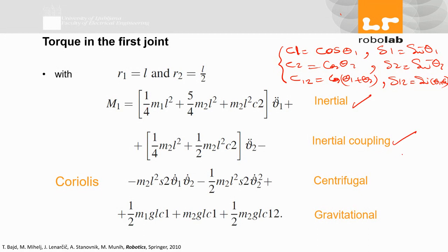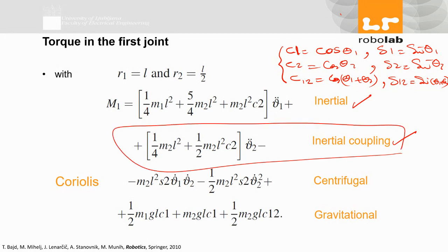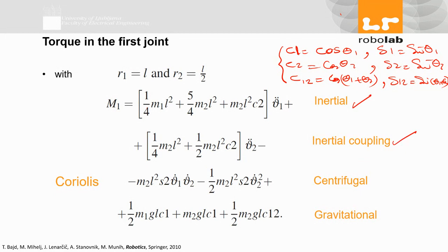Yeah, this one, we have it because they're connected, right? Yes. Because the first one is connected to the second one. And how did I figure that out? It's a connection, because here I'm talking about the torque at motor 1, at joint 1, but I see the second derivative of angle 2, which is related to link 2. So this is because I have a coupling between these two.